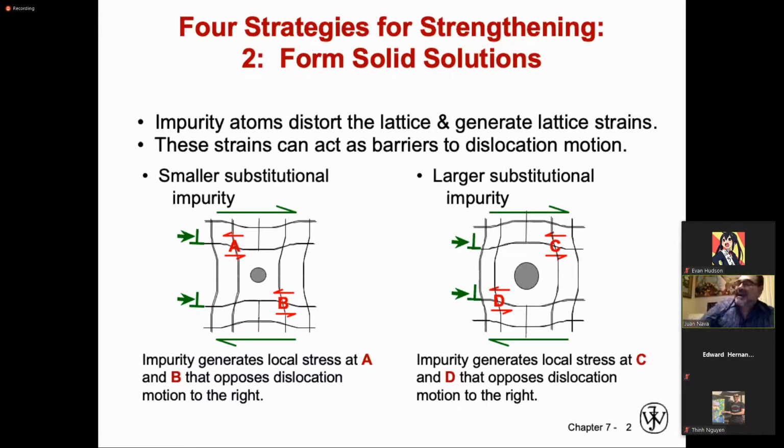I'm sorry. So forming a solid solution is at the bottom of your strengthening processes. At the bottom, because it doesn't give you that much engineering flexibility, and it's not going to give you the biggest increase in strength by just alloying. So on top of solid solution, you are going to have grain refinement. Grain refinement will be more effective engineering-wise, manipulating the process to control the grain size, to control the strength of the material.